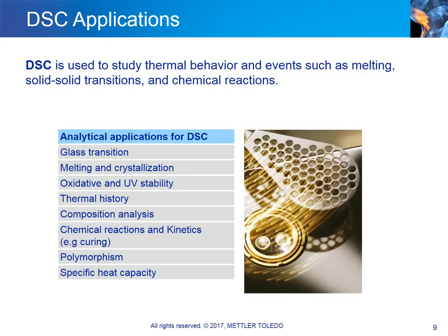The information obtained can be used to identify polymers, investigate the working range of materials, and for compositional analysis. Suitable methods can easily be developed for quality control and for the analysis of raw materials, additives, and fillers. Finally, the technique can also be used to evaluate vulcanization and other reactions.